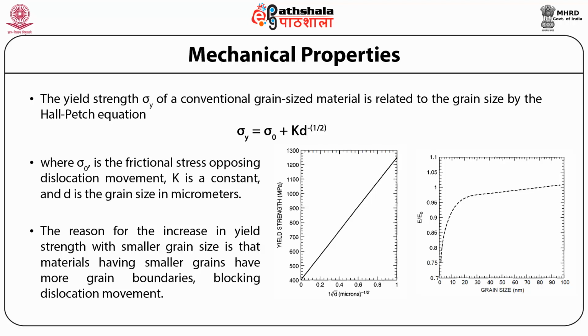Most of these measurements have been performed on consolidated particulate samples, which have large residual stress and flaws due to imperfect particle bonding, which restrict dislocation movement. However, nanostructured copper prepared by electrodeposition displays almost no residual stress and has elongation up to 30%, as shown in the figure. These results emphasize the importance of the choice of processing procedures and the effect of flaws and microstructure on measured